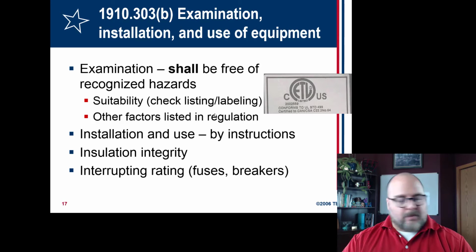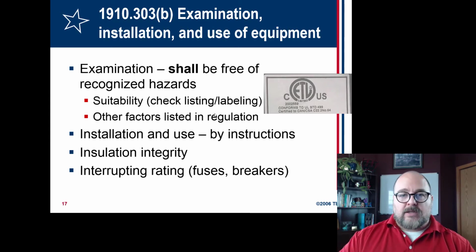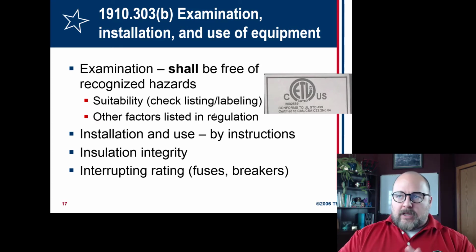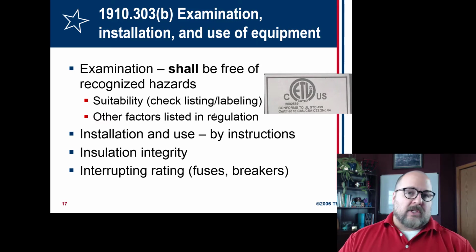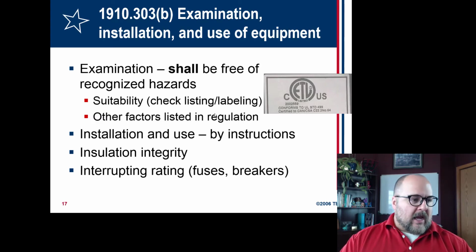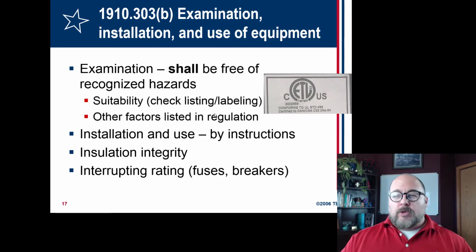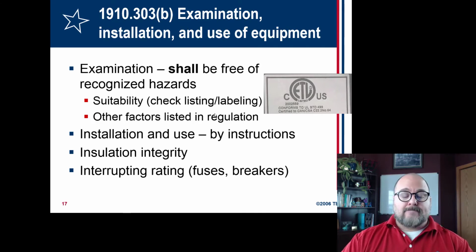For instance, a multi-strip, and I should have had one here to show you. You know what they are. Everybody uses them. Those are only designed for very low current, so you should only be plugging in TVs, computers, Xbox, things like that. Something that draws more current, like a refrigerator, a compressor, a hair dryer. These types of things draw more current. You should never plug those into a multi-strip. They're not designed to be able to handle it. And you may actually be using a multi-strip that's designed for a 15 amp max, but then you plug it into a 20 amp or a 30 amp circuit. So you would melt it before it would trip anything.